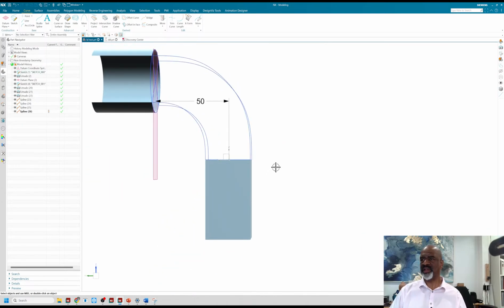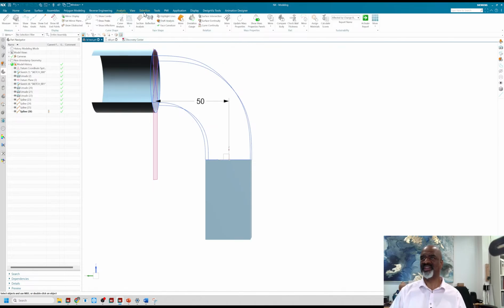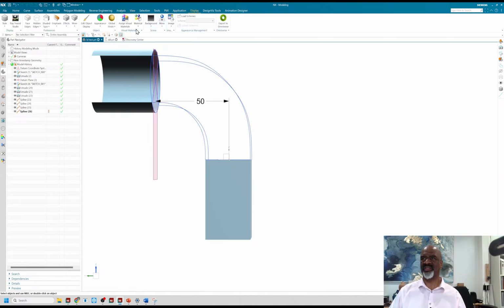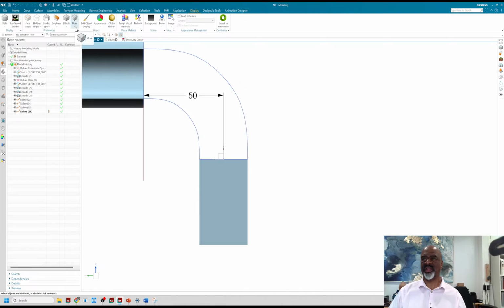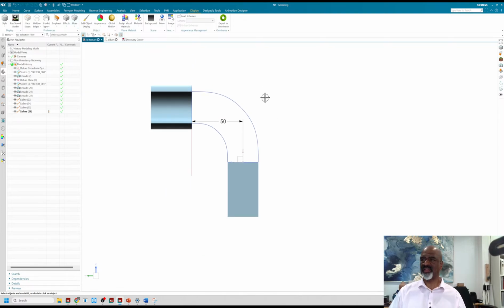I'll find that out by taking a side view that is not a perspective view. So let's go into view and turn the perspective off. And the perspective switch is, dagnabbit, it's in the display. I don't see the, oh, here it is. Yeah, turn that off. There we go. A little slow on that. Just don't use it often enough.